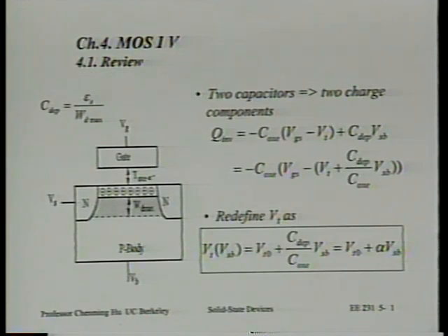That's our common notation. And under WD max is the neutral body. And this neutral body, as some of you know, sometimes is referred to as the backgate. Right? We have the backgate effect or the body effect, for example. And so I want to emphasize that concept. It's a backgate. It really serves the function as a second gate. We have a front gate, we have a back gate. All right? So keep that in mind.